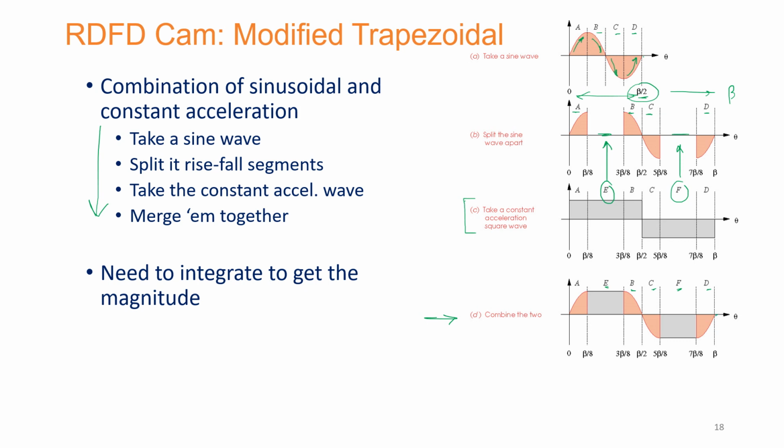And I should emphasize once again that we are still following the same procedure that we said: we're going to start from the acceleration expression, and then integrate it once to have the velocity, and then another time to find the expression for displacement. And we are going to take the same acceleration expression and take the derivative of it in order to find the jerk expression. So we are going to start from acceleration and build the SVAJ diagram around it. We are going to follow the same procedure over here as well.